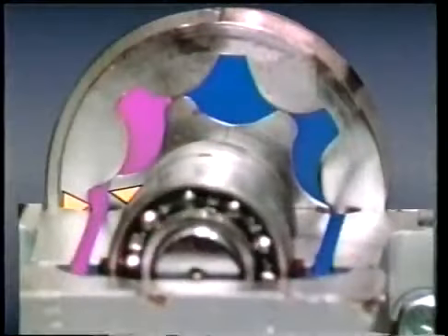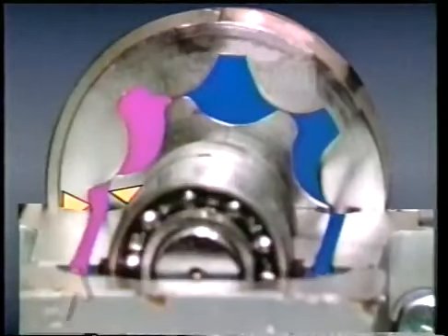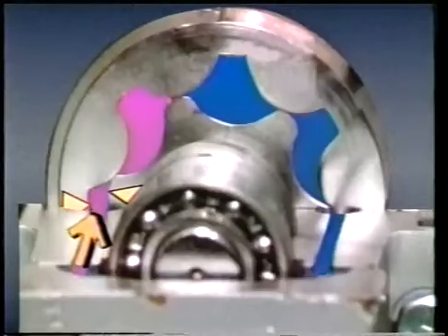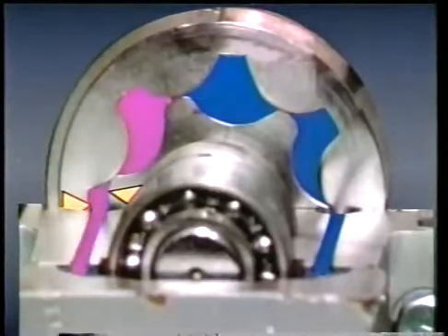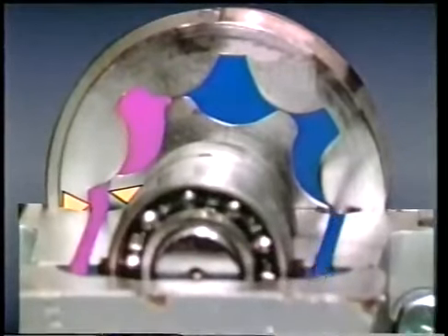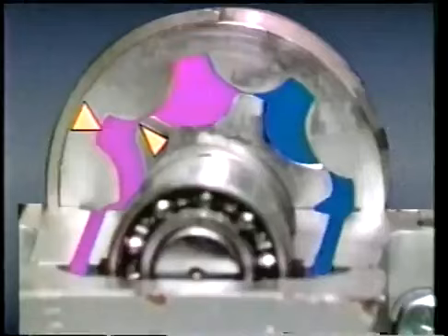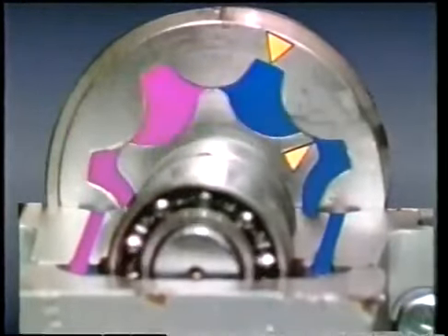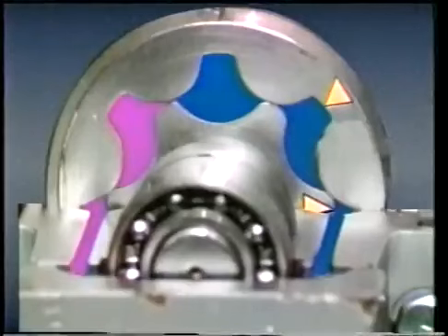The movement of the gears in the gerotor motor is similar to the gerotor pump. Pressurized fluid enters the port plate, pushing on one side of one tooth of both the inner and the outer gear. Since fluid on the outlet side is allowed to exit through the outlet port, there is very little pressure to oppose the gear movement, and both gears rotate. The torque developed is based on how much pressure there is at the inlet port and on the size of the gears.